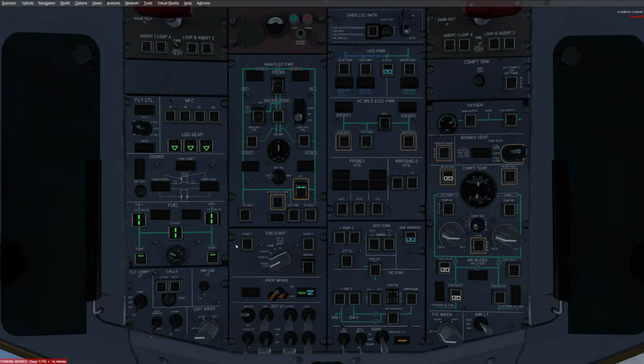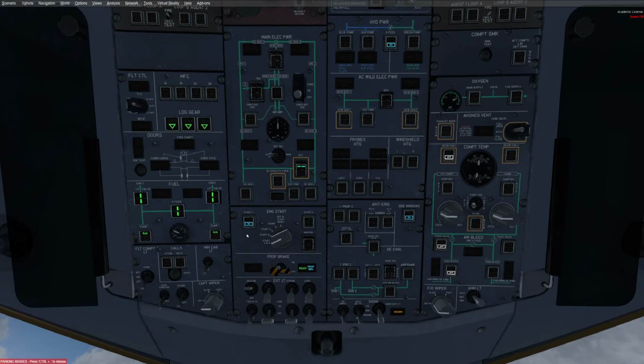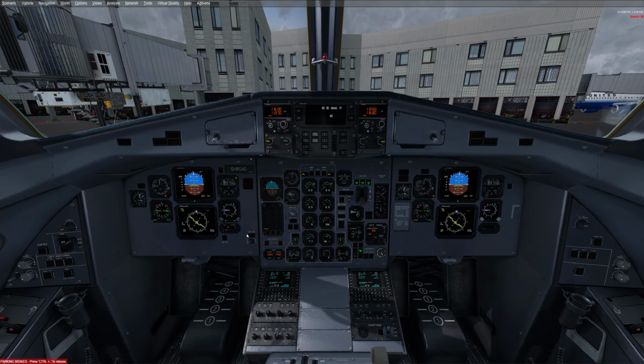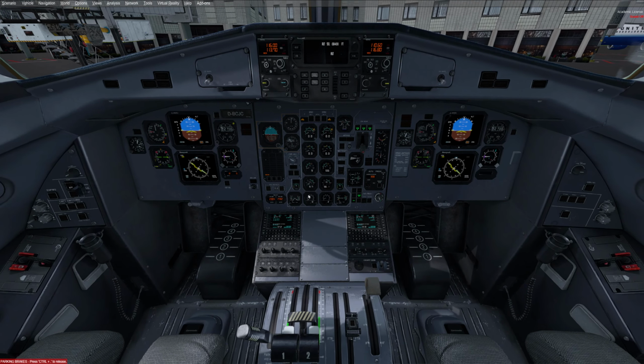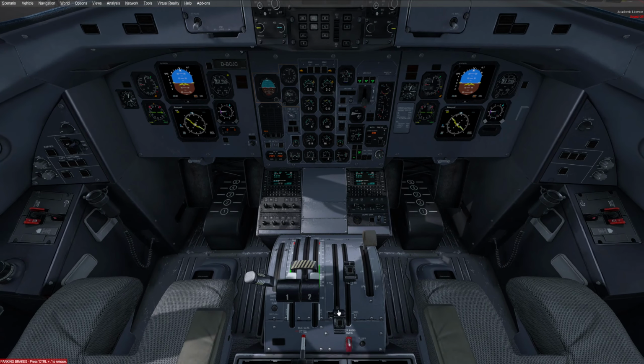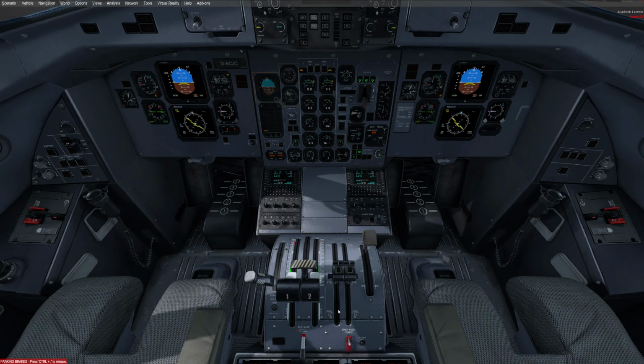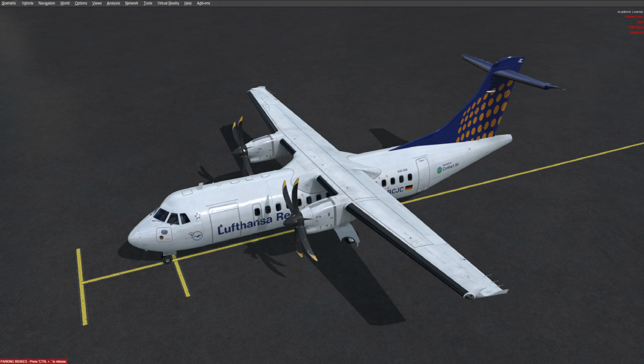Fuel pump 1, start. We're going to run down here to watch the NH run past 10. And when it does, we'll left click on the control lever number 1. And we can see that's going to fire off. Now we'll see a difference outside. This prop is still not turning, but this one will soon start to turn. And you'll see that the brake is the effective difference.